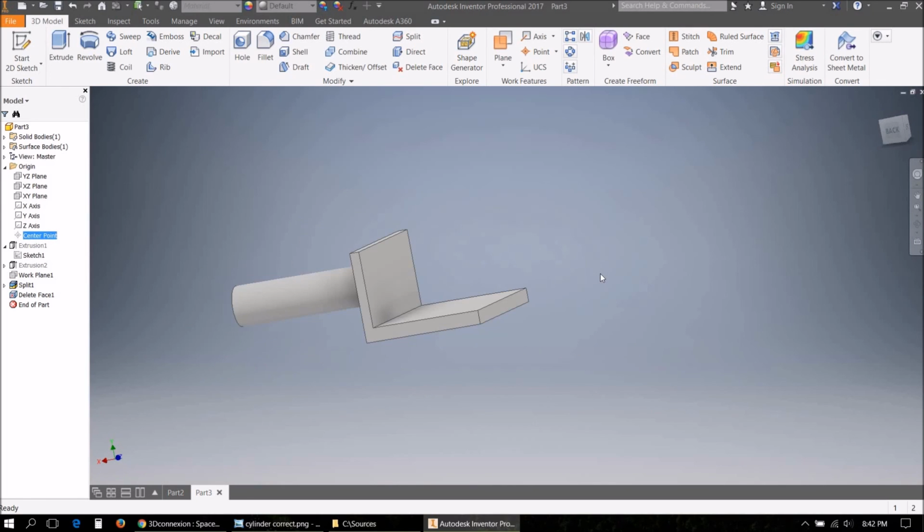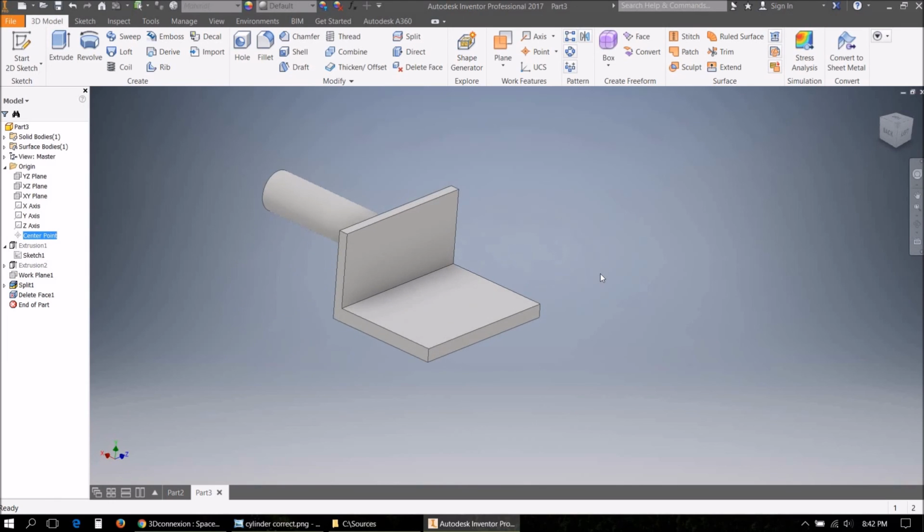Okay, next, materials. When you are creating the high resolution model, you can use as many materials as you want. The materials in Substance Painter don't have any performance cost if you apply more of them. Normally, if you apply more materials in 3D Studio Max or in Unity, this is not good for performance. However, in Substance Painter, multiple materials on one object are simulated using different parts of the texture. So this can be easily transferred from Inventor to Substance Painter by the use of ID maps.